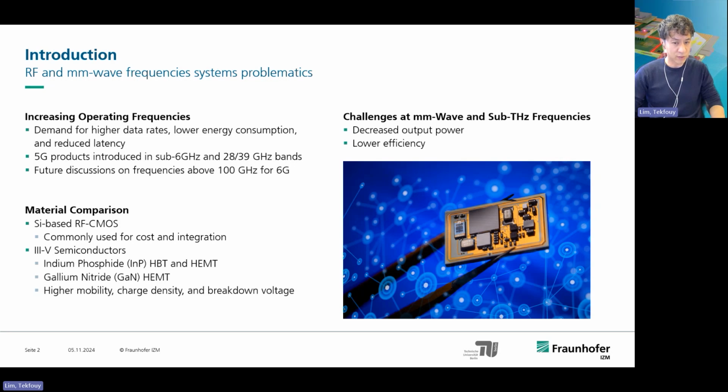But in parallel, there are a lot of studies on III-V semiconductors, with indium phosphide, for example, the HBT or the HEMT transistors, or also gallium nitride, but also silicon germanium. These technologies are really developed because they present really good properties, with higher mobility, higher charge density, and also a really good breakdown voltage.